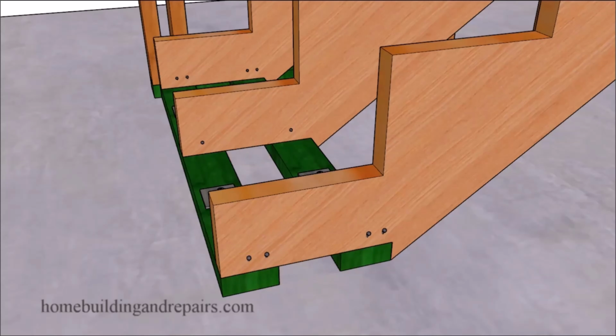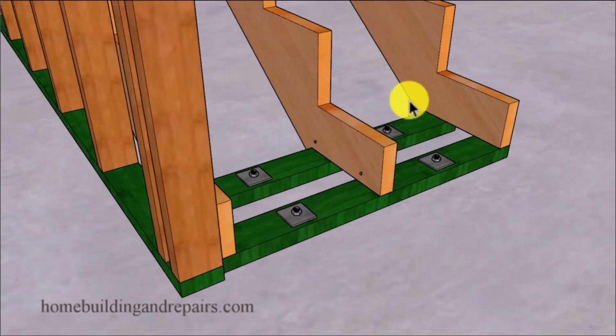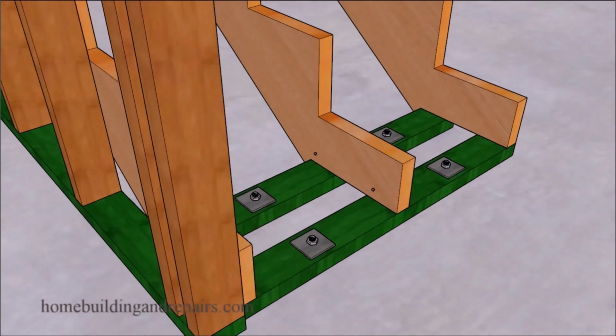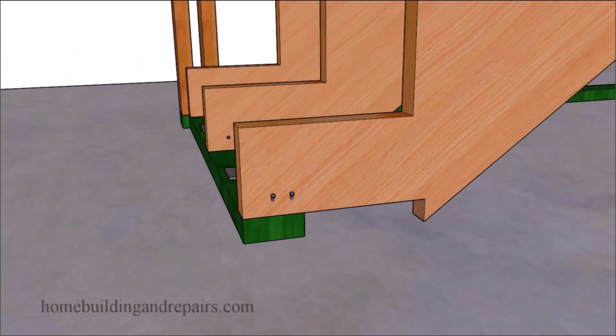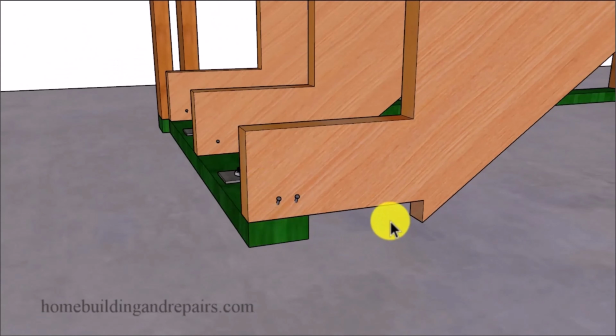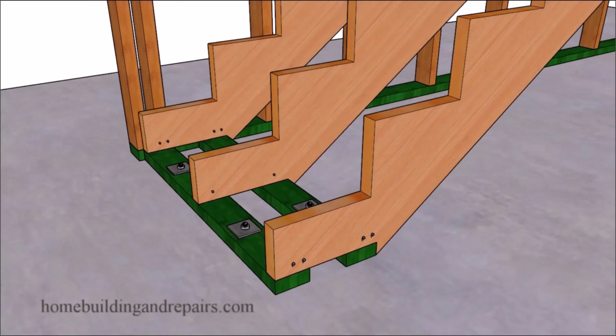And if that one seems like too much work, what about this one here? Install the framing plates like I would like to see them installed and have a notch at the back of the stringer, providing us with another method that might work better than the second example in the video. You're going to be able to use two framing plates to attach the stringers securely to the foundation, and have your notch here to prevent the stringers from sliding forward, if this is actually something you believe will happen, again, even though I've never seen it happen.